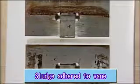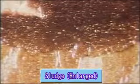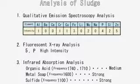Let's zoom in on the sludge adhering to the vane. This resin-like sludge colors the parts and causes friction. It can also solidify into a plastic-like material, making it impossible for the machine to run. An analysis of this sludge reveals that it is composed of trace quantities of metal and minerals, semi-solid metallic soap, and liquid organic acid.